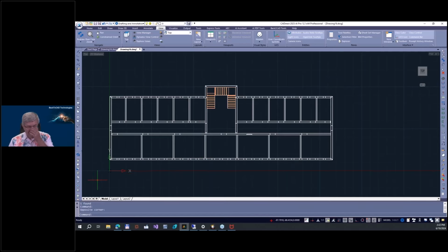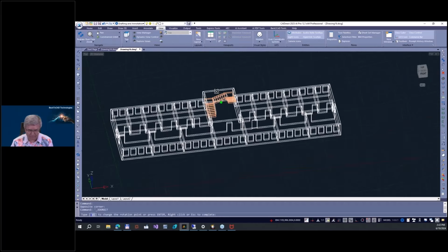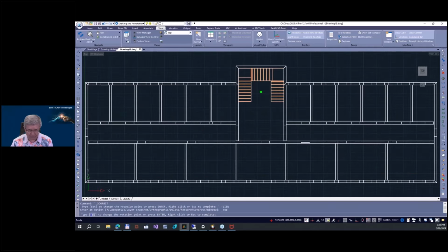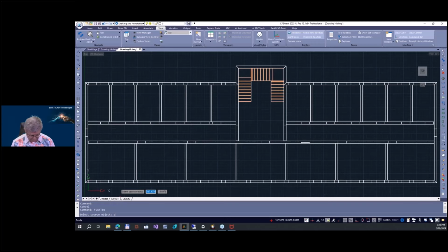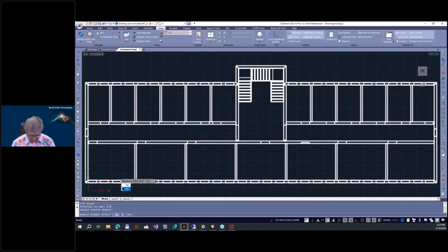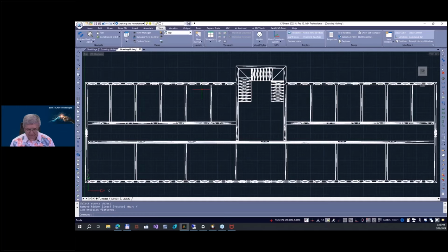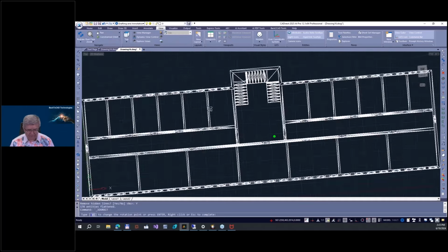Okay. So now, if you see, this is a three-dimensional drawing. So go to the top, and this is normal DWG. Now, if you need this drawing as a two-dimensional drawing, you can use our internal function flatten. Okay, but I show you something. There's one problem. Yes, remove hidden lines. Yes. So this is now a flat 2D drawing.